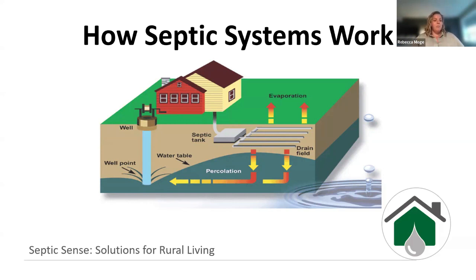A lot of people feel that the sewage that goes into the ground is mostly dealt with through evaporation, but actually only about 5% of the sewage evaporates. The rest of it relies on the soil to be treated appropriately. So again, underlining the importance of proper designs, installations and maintenance, because the majority of it relies on the soil in order for that appropriate treatment to take place.